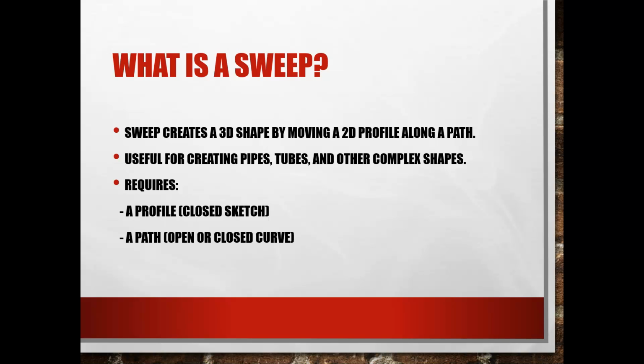But when we're talking about AutoCAD, you have to make sure that it's a closed profile, right? We've got to make sure that it's joined together. Remember that if you don't join them together, it's going to make surfaces. So make sure when you're using AutoCAD that you select that profile once you're done and go ahead and join it, and then you're going to verify that it is joined, right?